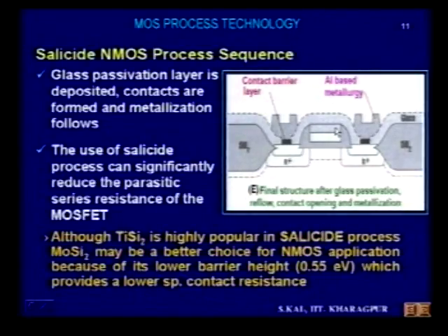The combination of oxide, polysilicon, and silicide together forms the gate region. The contact of the source region is not a metal contact here, but a silicide contact. Since silicide formation is automatic, a self-alignment process is used here, and automatically you can get a device size smaller than in the earlier process. This is the salicided NMOS process.